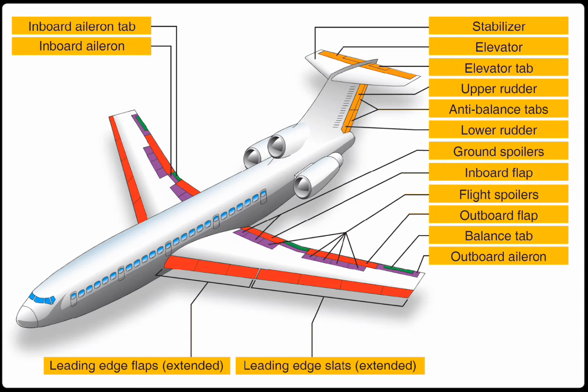What is a fair lead? Cable guide that slightly deflects. How much cable deflection is acceptable due to a fair lead? 3 degrees. Where does failure of cables occur most frequently? When cables pass over pulleys and through fair leads.